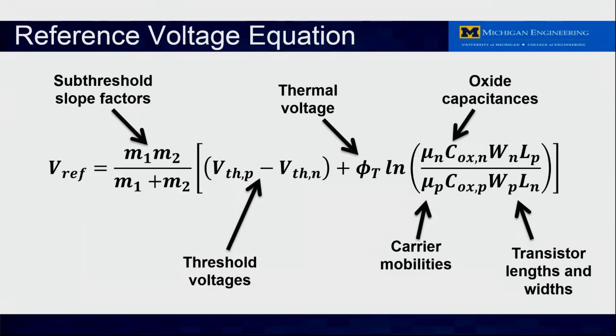Let's again consider the voltage reference output equation. The output voltage depends on the difference of the threshold voltages, rather than on the absolute values of these parameters. Thus, if the threshold voltages vary, the relative change in each voltage should approximately match that of the other voltage, thereby reducing the effect of threshold voltage variation. We can ensure that this tracking occurs if the layout for these devices is done very carefully.